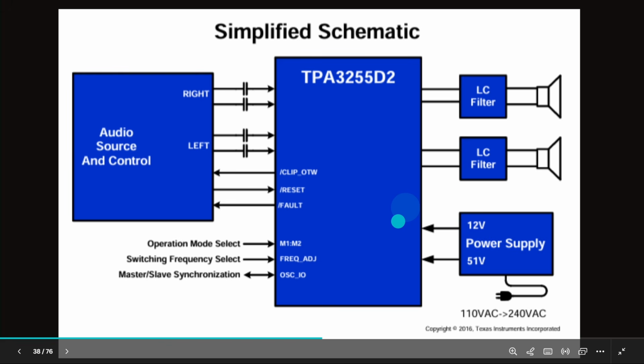Preamplifier circuits. A well-designed preamp stage is critical. The NE5532 operational amplifier is a standard choice widely used in audio applications for its low noise, high output drive, and minimum distortions. Its excellent DC and AC characteristics make it ideal for high-fidelity systems.